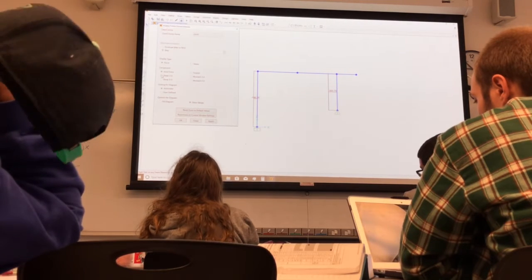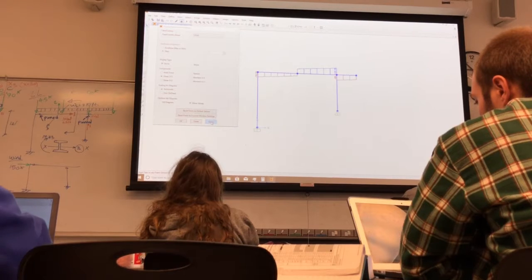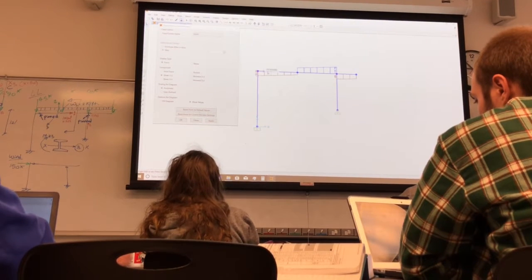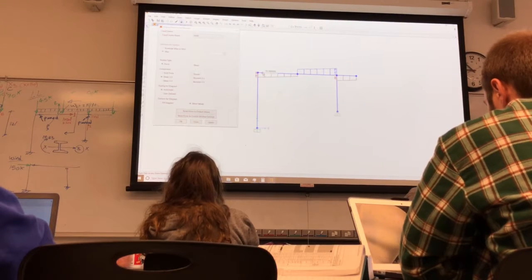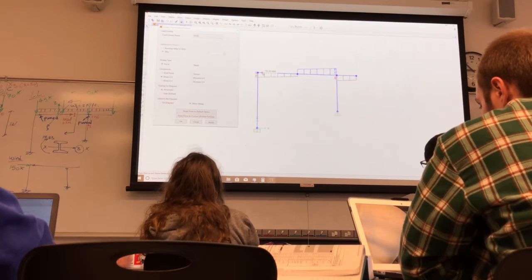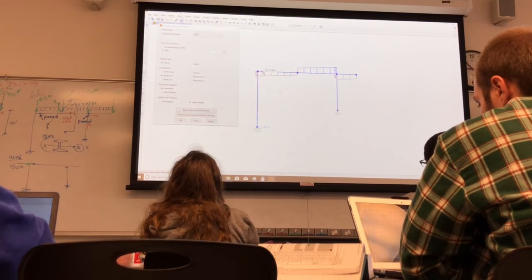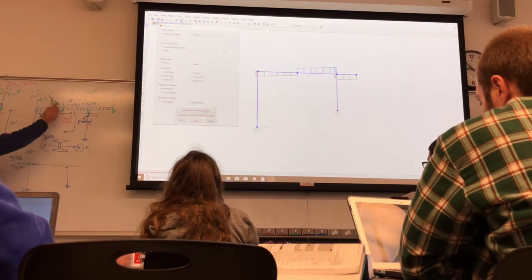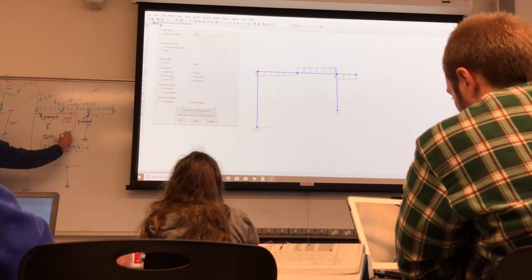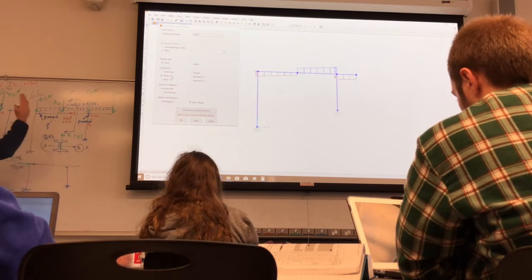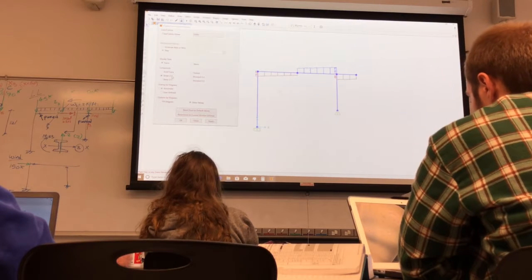And you can see the shear diagram too. That's based on dead load. So you see the shear diagram looks familiar, right? That's how a shear diagram looks. It's just the sign convention is different than what you're used to in analysis, structures 1. Shear is shear 2, because that's the local axis. Shear is shear in the y direction because that's axis 2, so that's the y. So we're talking about shear in the y direction. And then we're interested in the moment in 3, M33.